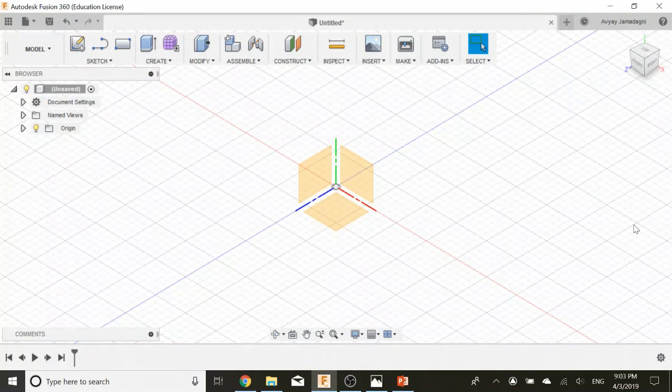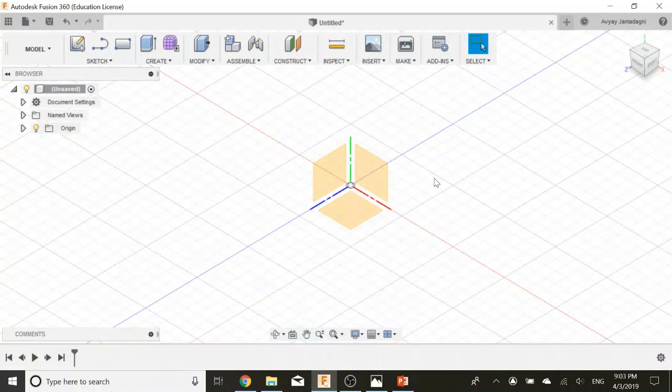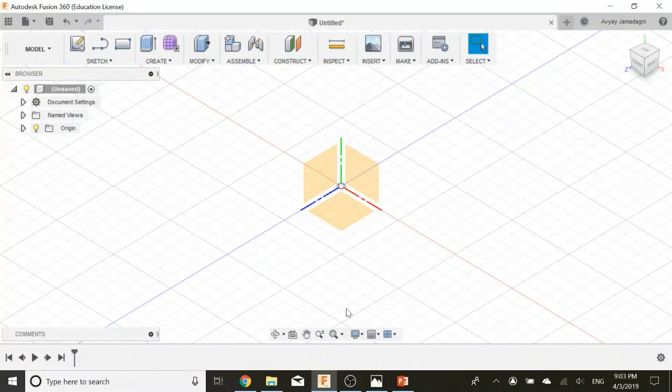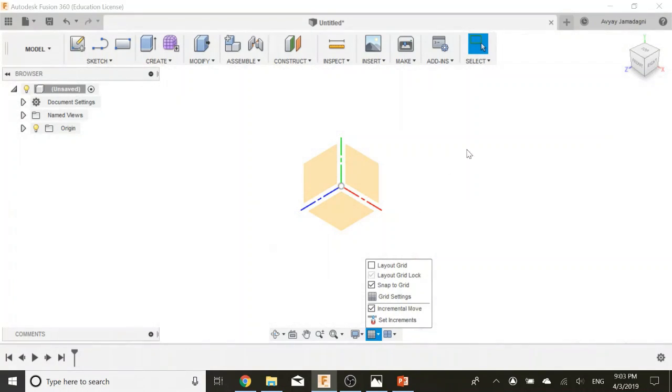Okay guys, so when you first open the software, you should get a screen like this. And this shows, yep, you're in the right place. Now, the first thing I'd like to do is remove this layout grid in the back. Now, there's nothing wrong with it, but for me, it's just annoying. So to do that, let's go down here to Grids and Snaps, and let's uncheck Layout Grid. Do that, click on the white space, you're done. And that's about it for this lesson.